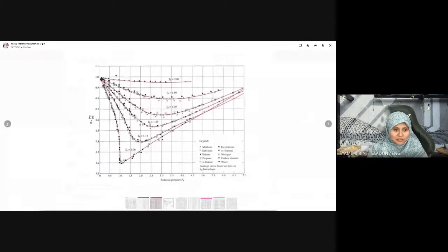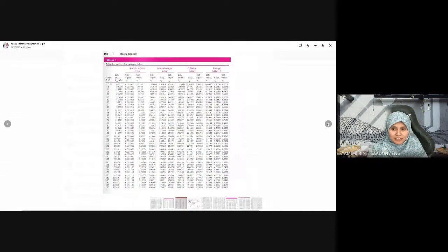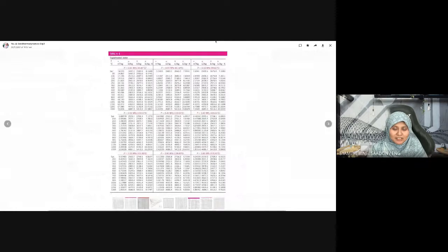This one, A6, right? As said earlier. This is not A4. Okay, if you say A6, that's fine. Where do you want to look? The value of H1. At state 1, air at 100 kilopascal, temperature 280 Kelvin. We have the pressure and the temperature given, so we are going to search for the enthalpy H1. Which one should we use?